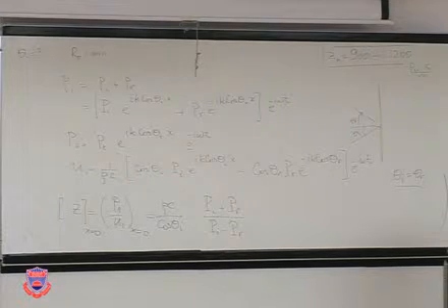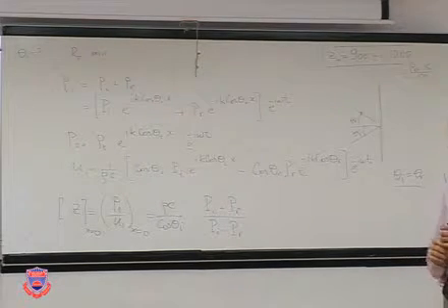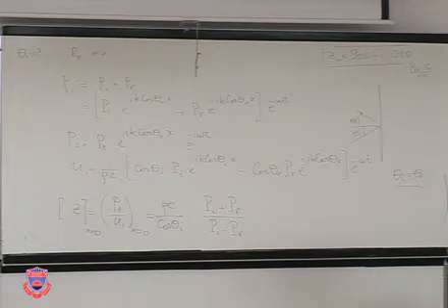I use this equation, but here the question is how am I going to use the complex impedance? Exactly. Do I need to use real part, or do I need to find magnitude of the impedance? I found the magnitude of the impedance on surface, and I substitute the value into the reflection coefficient equation.